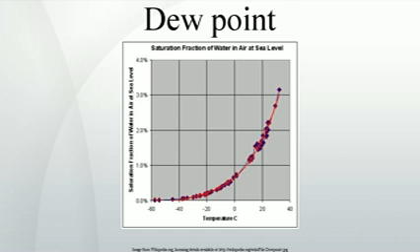In the same way, increasing the absolute humidity after a temperature drop brings the dew point back down to its initial level. If the temperature rises in conditions of constant pressure, then the dew point will remain constant but the relative humidity will drop. For this reason, a constant relative humidity percent with different temperatures implies that when it's hotter, a higher fraction of the air is water vapor than when it's cooler.